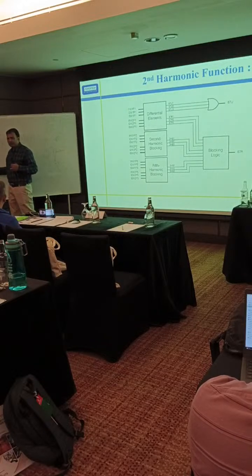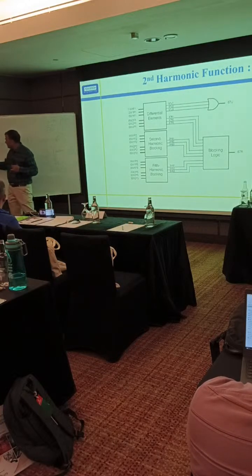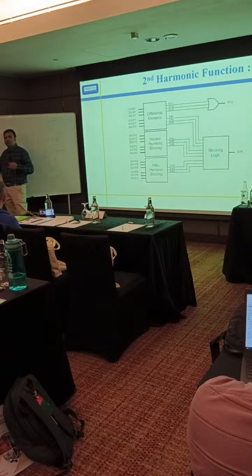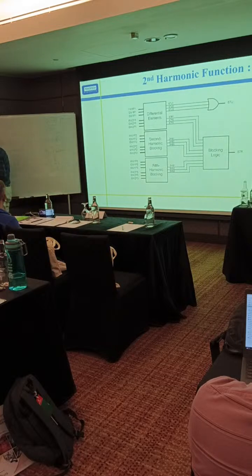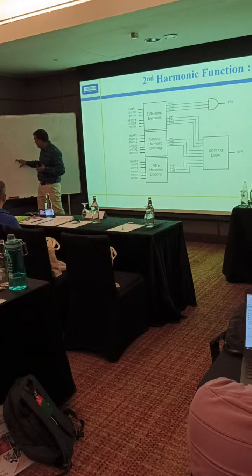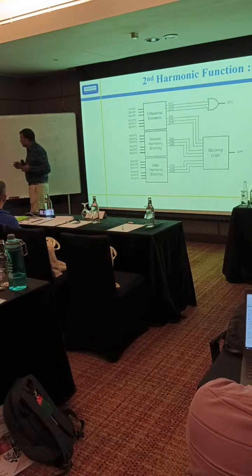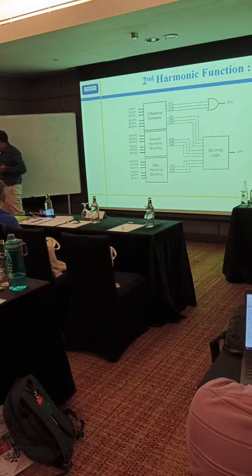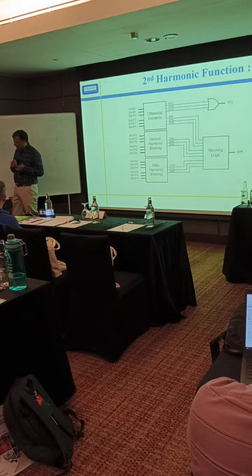Okay. But when differential current is more than the set limit here, this is called unrestrained. Restraint means it is restricting. Unrestrained means it is independent. So as soon as the differential current value is more than this value, we do not consider this value. Immediately trip.